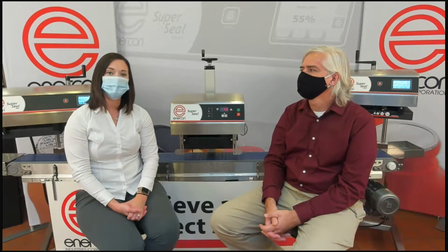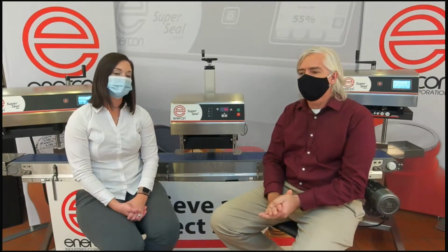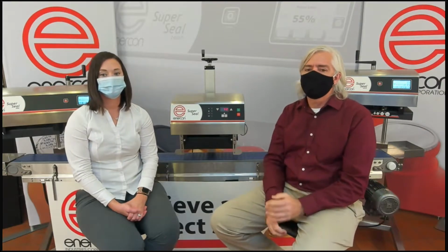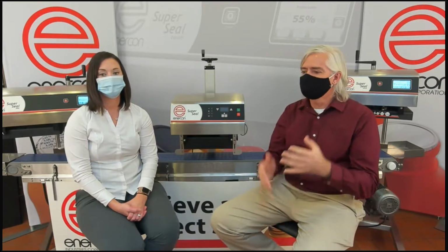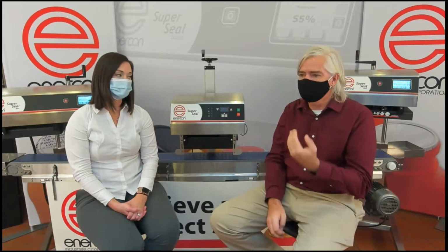So we've looked at no seal and partial seal troubleshooting. Is there anything else that we should go through? Yes, we've got one more scenario really. Many packaging operators feel that if some power is good, more must be better. That simply isn't the case. So you're saying if you don't establish the top of your operating window, you can run into problems? That's right. You can see foil wrinkling. You can damage the underside of the liner. Scorched pulpboard can happen, and sometimes it just stinks. And nobody wants that in their package. Thanks, Jeff. So we have one more video for you that's going to go into what can happen with overheating.